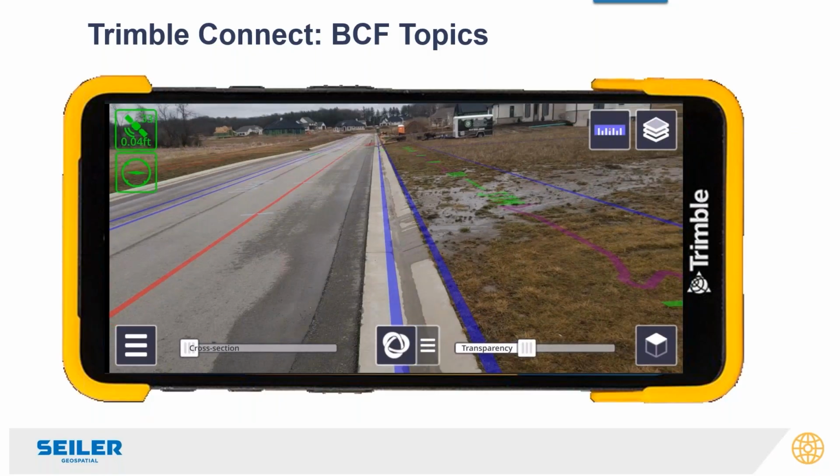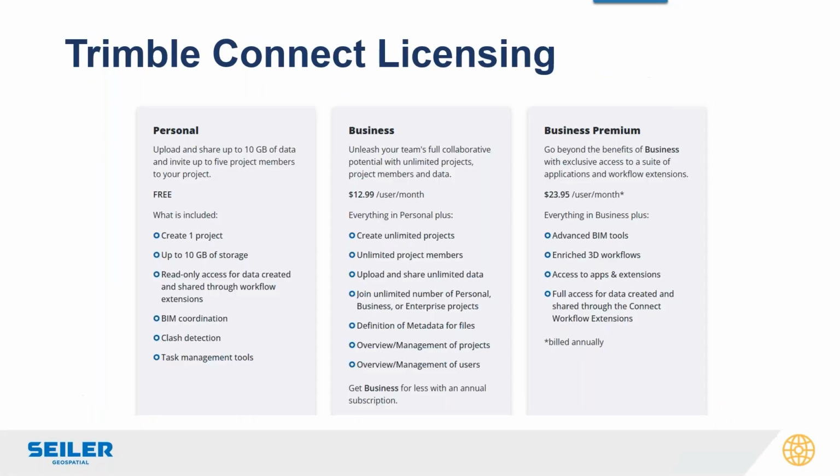for the most part. So that's a quick Sitevision demo, and I think out of all the survey software, Sitevision does integrate with Connect the best. So again, if you don't georeference, you don't do things properly, that model's not going to look very good out on site. Or you could manually place it too. That was a real quick example of Trimble Connect and with that, TBC, Access and Sitevision.